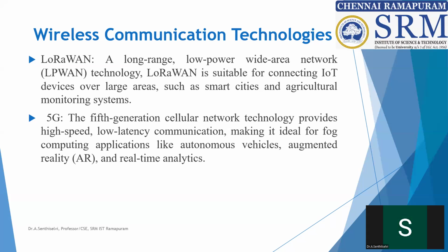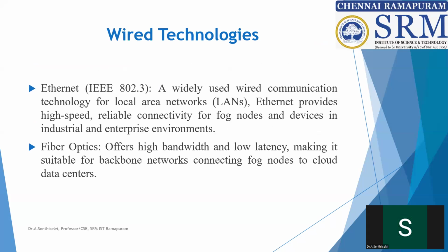Next, we are moving to wired communication. Under wired communication, the first one is Ethernet. For this one, the IEEE standard is 802.3. It is a widely used communication technology for local area networks. It provides high speed and also reliable connectivity between the fog nodes. Mostly, this is used in industrial and enterprise environments.